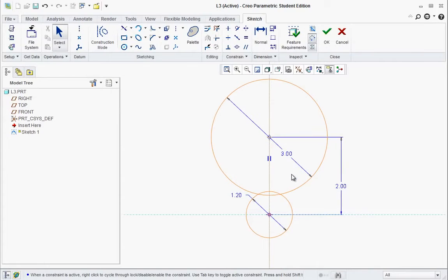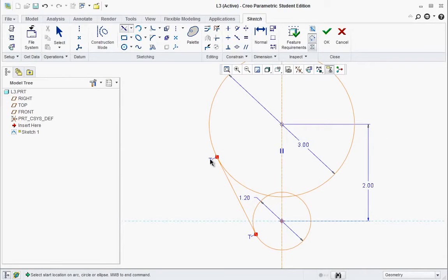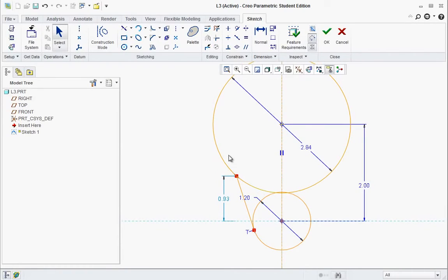Alright, at this point, now I can actually use that tangent tool. Select this line, and then you could connect, just draw it over here. Wants to go tangent on both, but that's okay. We'll just make it tangent on both. Then what we do is we just delete that T there. Click on the T. I middle clicked a couple times to get out of the mode, and then delete that. At this point, now you can see that top arc is not supposed to be tangent, so that's good. We just want to move it down a little bit.